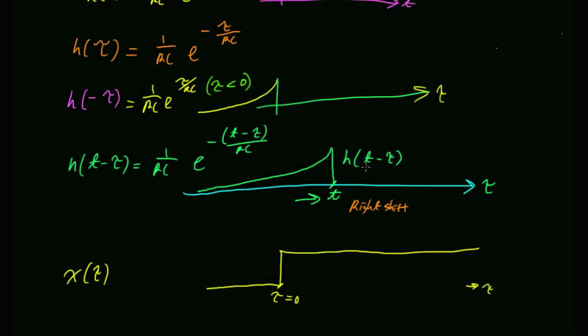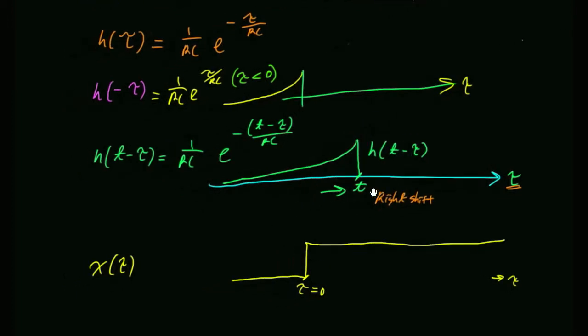Okay, so look at the convolution integral. The convolution says to take x and h of t minus tau and multiply them. Isn't that the very definition? The convolution says integrate x of tau, h of t minus tau over all values of tau. So if I multiply those two functions together, where is the non-zero integral? Do I need to integrate negative taus? Why not?